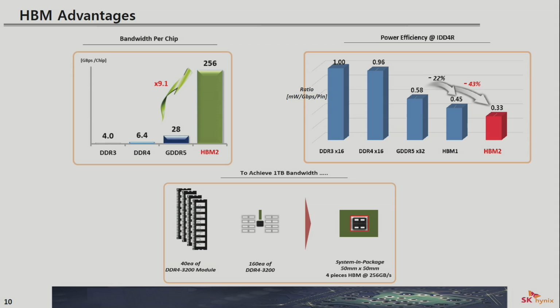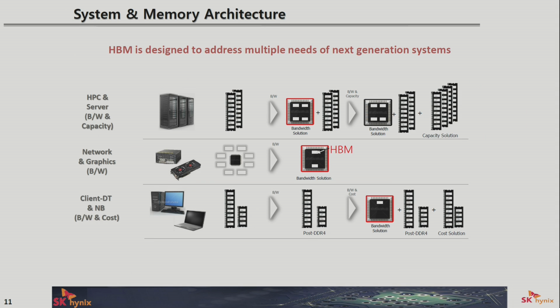For these benefits, we're seeing HBM technology being adopted across the industry. In high-performance computing as well as servers, HBM essentially acts as an L4 cache, albeit with very high bandwidth and much higher density than an embedded cache can provide. And in cases where the processor requires higher density, it can always get that from an external DRAM source like a DDR4 module.